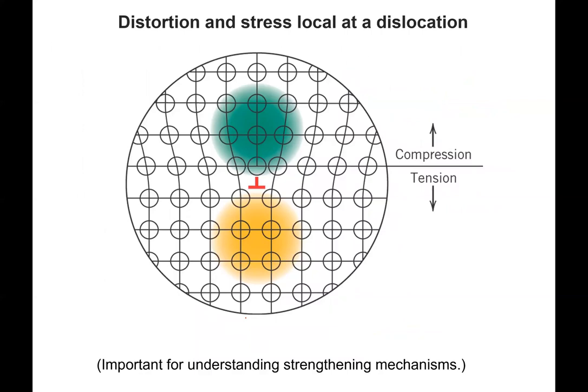So first thing we can do is ask why or how the dislocations interact with each other. So here we've got an edge dislocation. We can see that extra half plane here. And if we think about the region around this dislocation where the core is, it's coming in and out of the board, making the line, you can see that the atoms in here are all closer spaced than they would be if we move away from the dislocation.